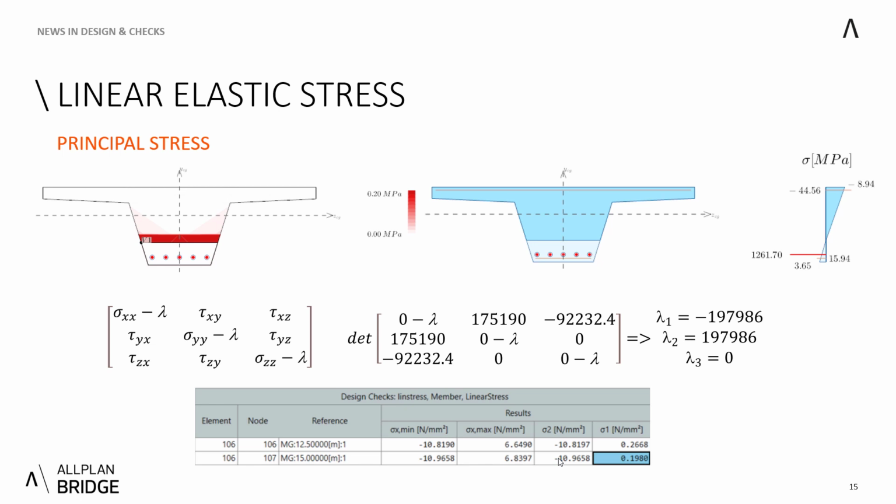And on the right side, there is this corresponding normal stress result. So how do we get there? As I mentioned to you, there is this calculation of shear stresses, which we now go with into this matrix and apply tau xy and tau xz, and we can use that they are equal to tau yx and zx.